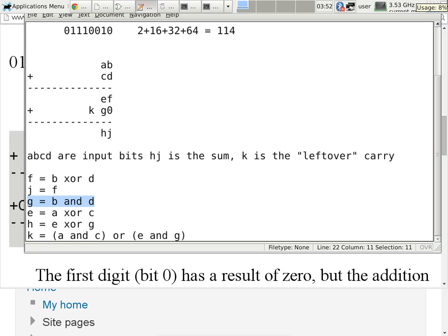So that's why when you work on this homework assignment, I don't want you to specify gates the whole time, because this whole thing is one single functional unit. It has 3 inputs, 2 outputs, and this is how you stack them. And once you know how to stack them, making a 16-bit adder is really just a matter of slapping those things on, like 16 times.